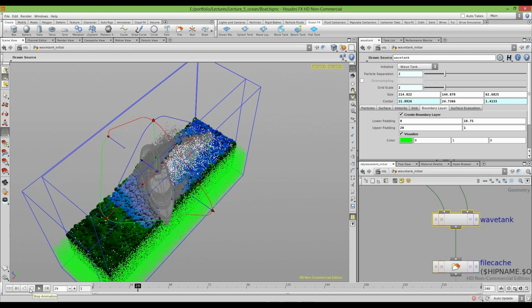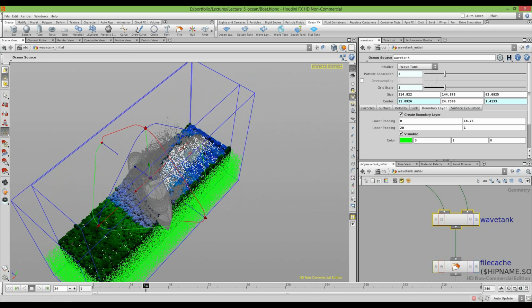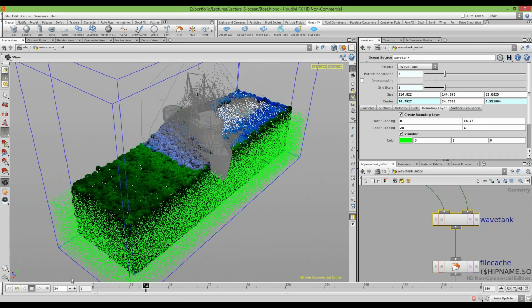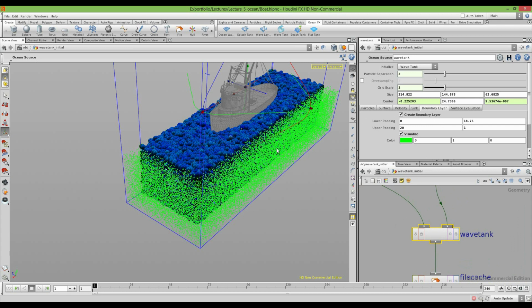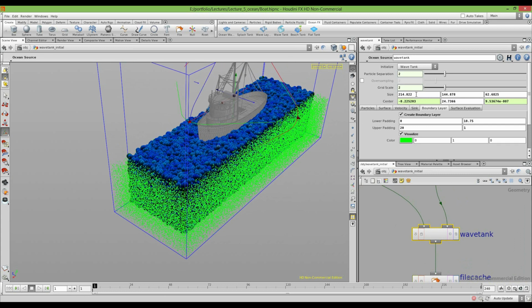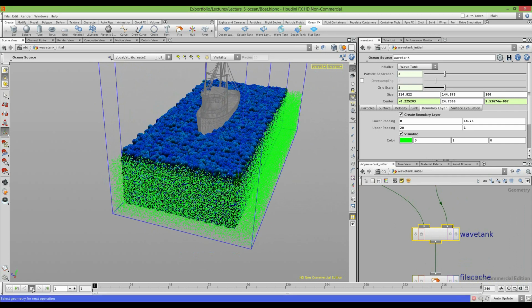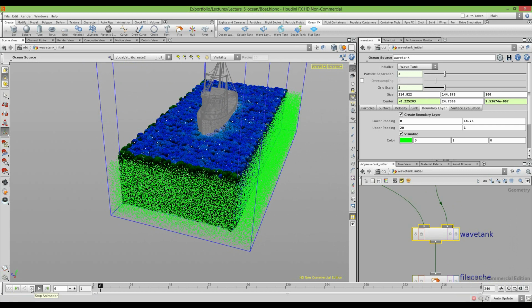Looks like that animation, the tracking happens only in translation. So when I do a rotation, it doesn't work. So okay, to solve this problem, you need to increase the size of the fluid tank. So let's say X, Y, Z. I need to make it bigger on Z axis. Let's say 100. Okay, great. So now I can make a turn without any problem.